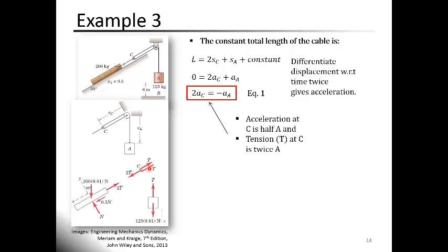We have another tension here because this side of the pulley is attached to the center of this pulley, which is fixed, so we have kind of a reaction force. If we are studying this statically, we have tension T here and another tension T here.